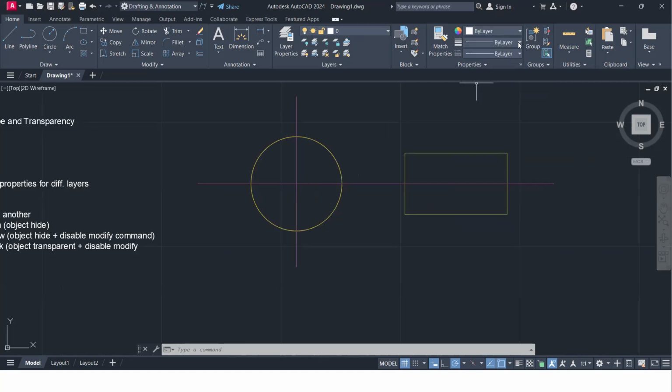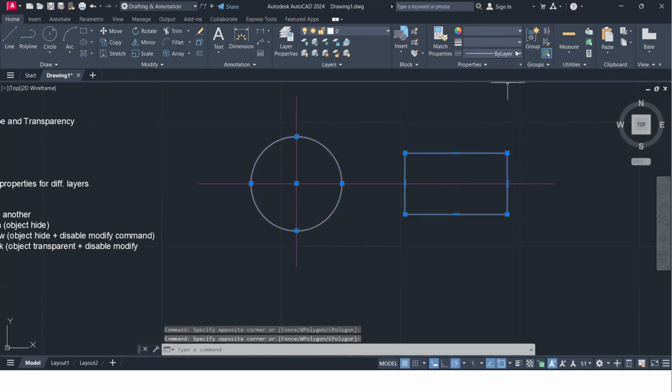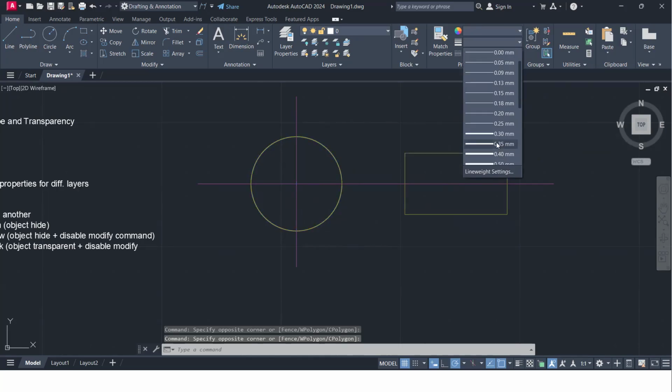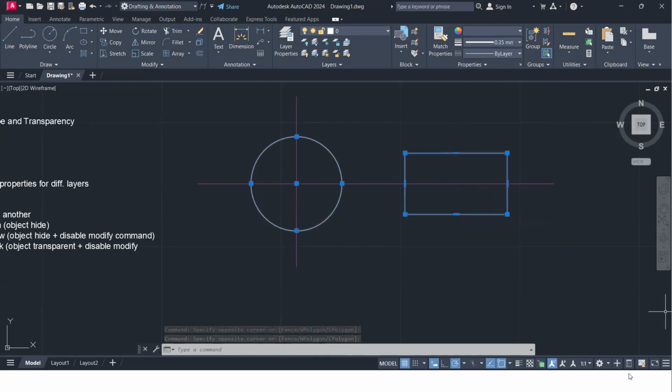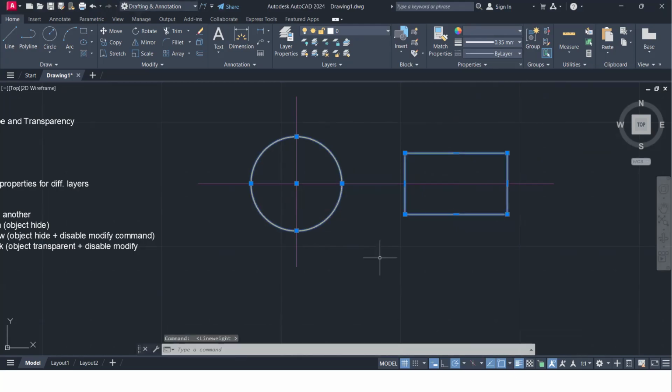Then come to the next part. Next one is your line width. Suppose you want to emphasize the object. What you do is right here increase the width of this line, and also for this line. For the object line I want to set the width here. For showing the width, we use the show and hide line width option. Click on this part, then your line width will be shown, and then hidden. And then here we get the line width.